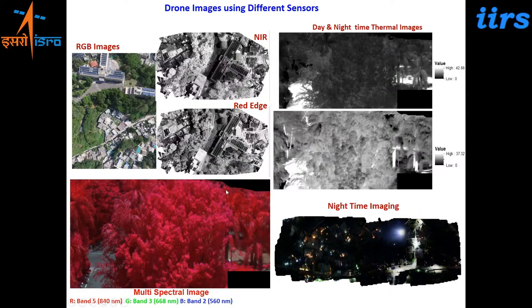Then a contour of 1 meter interval could also be generated. A detailed slope map was generated. A topographic map of 1:2000 could be generated. See, if you can see the contours along the built-up areas, along the mango orchard, so different height levels of the mango tree itself, single mango tree could be captured, and the elevation information can be obtained here. So slope map of these areas were generated, and also a complete 3D picturesque view could be generated.